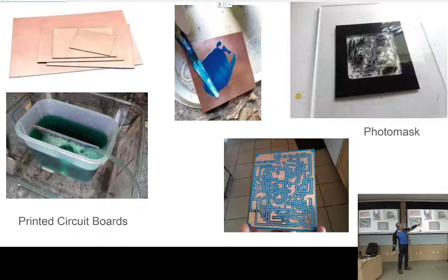And then you expose the light through the photomask, and then you go through several chemical processes. Finally you have the photoresist only where the light touched or where the light didn't reach. There are two kinds of photoresist. And then you put it in acid. The acid part is the same thing if you do silkscreen. Now the great advantage of this over the silkscreen is that you can have very, very fine details. The silkscreen is limited by the threads crossing.